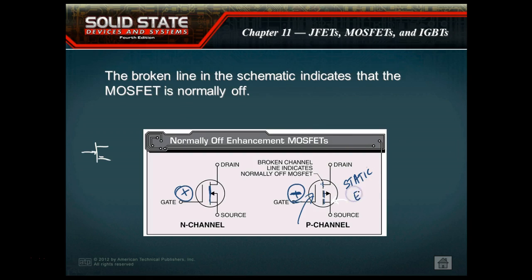So what I'm going to show you is some of the things we have to take into consideration when we deal with MOS circuits. You got to be a little careful with them. You can't handle them directly out of the pack. You got to be careful, make sure you're discharged, or make sure you and the MOS circuits are at the same potential. So when we come back after Thanksgiving, I'll make a point to, and if I don't, remind me to show y'all some of our static mats and some of our wristbands and stuff that we use when we handle MOS circuitry.